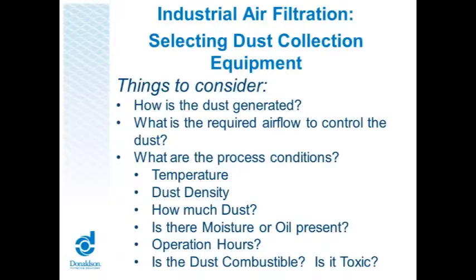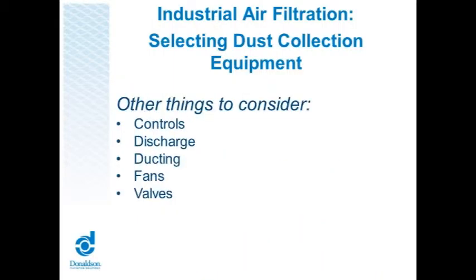And then moisture or oil, because that is a huge problem in a dry dust collection system, because that'll make things sticky, make things messy, make things clump up and cause problems. So understanding those things will help you pick the right collector and make sure that your customer's happy at the end of the day.